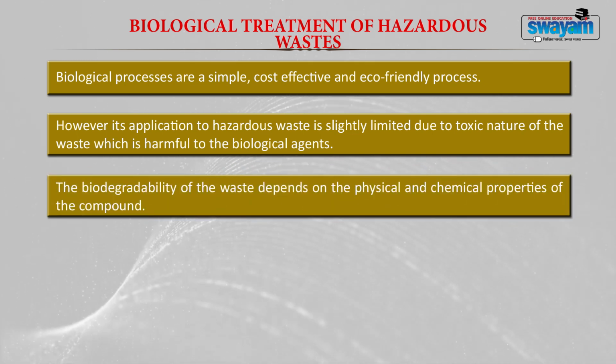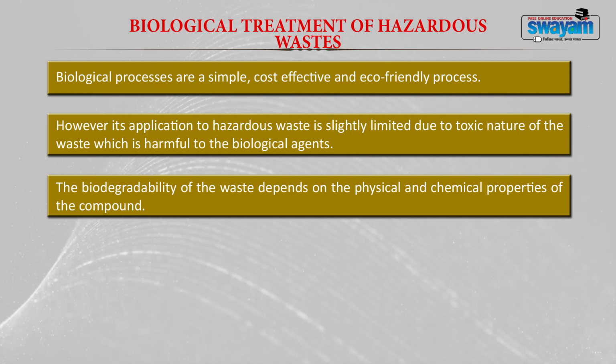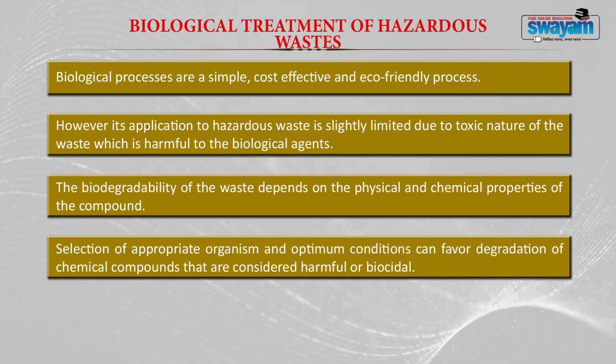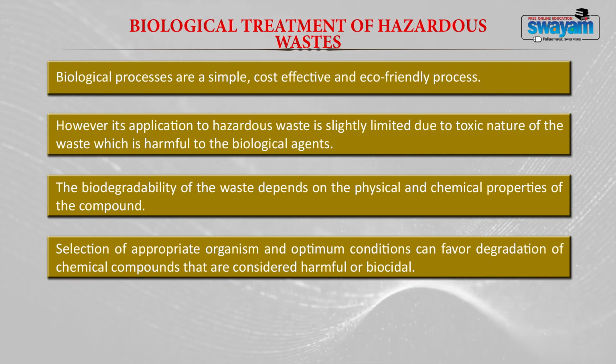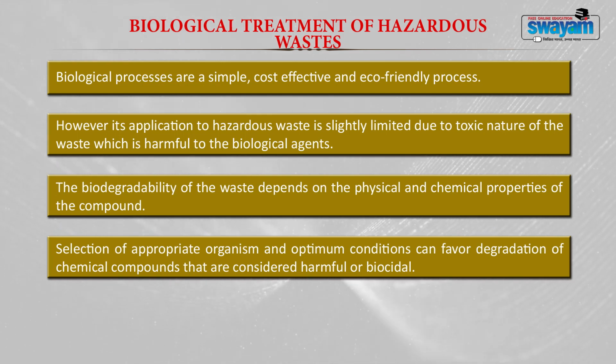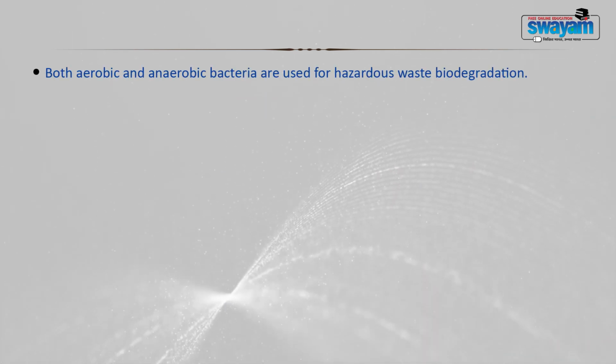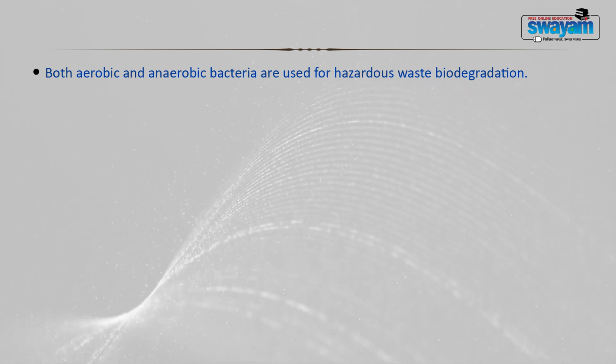The biodegradability of the waste generally depends on the physical and chemical properties of the compound. Now, selection of an appropriate organism and optimum conditions will generally favor better degradation than chemical methods. An example is phenol and phenolic compounds, which can be treated if you properly acclimatize the biological agent to the hazardous waste. You can use both aerobic as well as anaerobic bacteria for treating the hazardous waste.